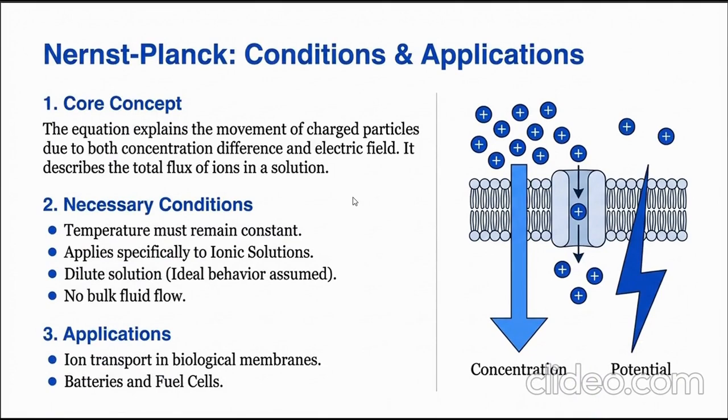When applying the Nernst-Planck model, we assume a dilute solution and often neglect bulk fluid motion to focus on the migration-diffusion coupling. This equation is a mathematical foundation for analyzing concentration polarization in fuel cells, batteries, and reverse osmosis membranes.